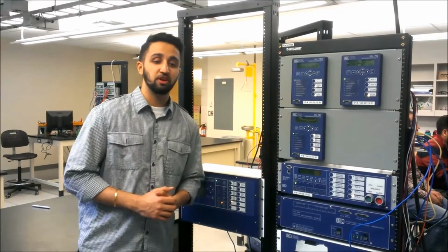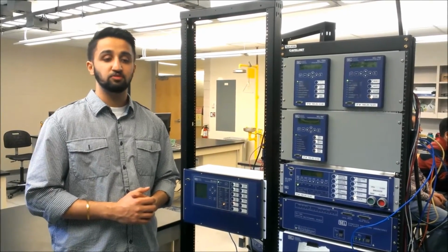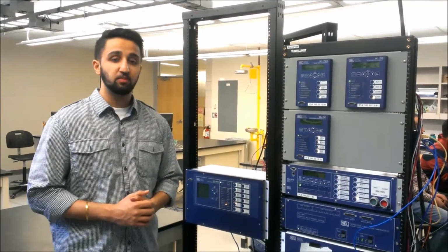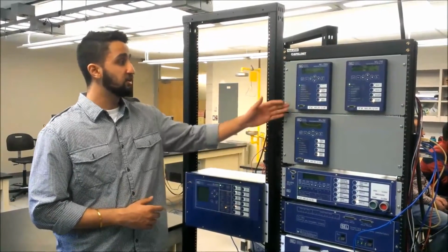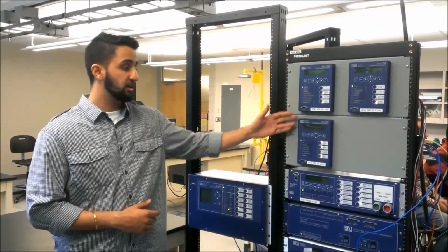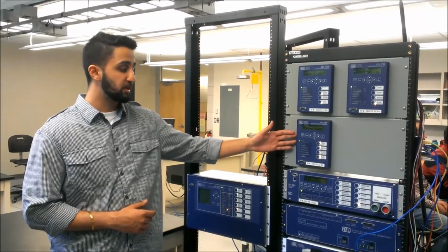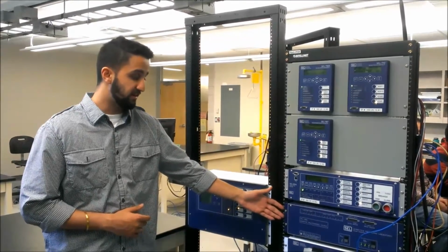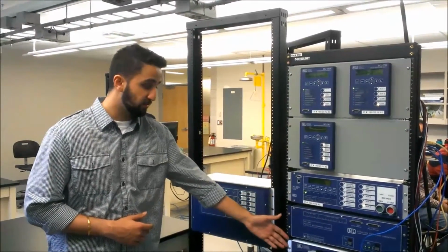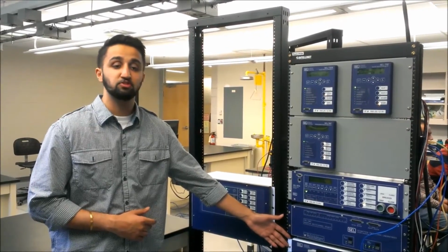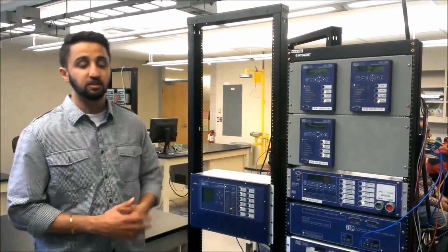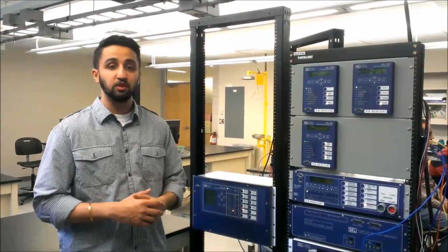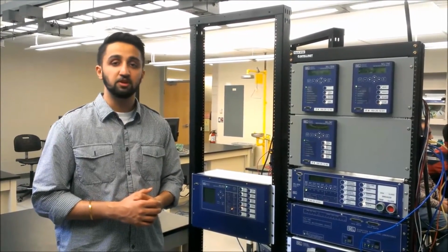In our Energy Engineering lab, we have set up our SEL relays to demonstrate GOOSE messaging. Our SEL component setup includes the SEL 751 feeder protection relay, SEL 787 transformer protection relay, SEL AMS adaptive multi-channel source, and SEL 3530, which is a real-time automation controller. All these devices are on the same time reference, and we have accomplished this by using the Arbiter satellite clock.